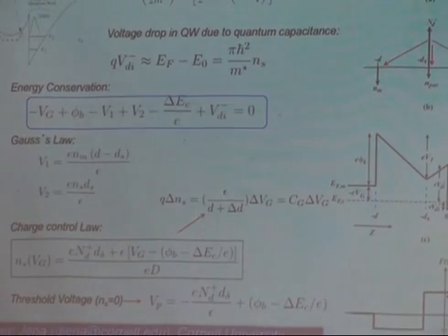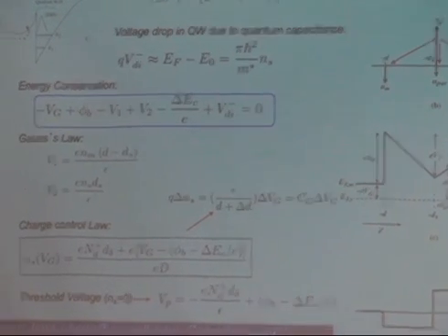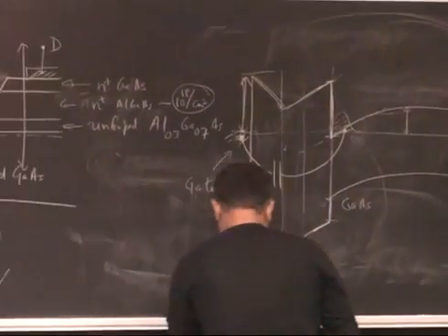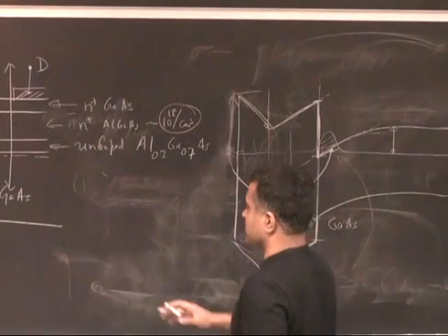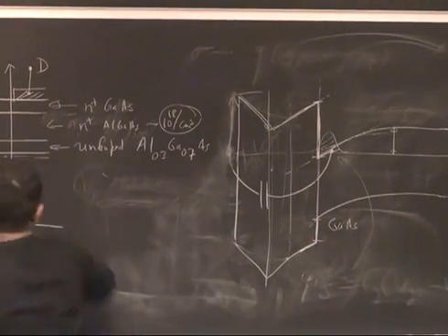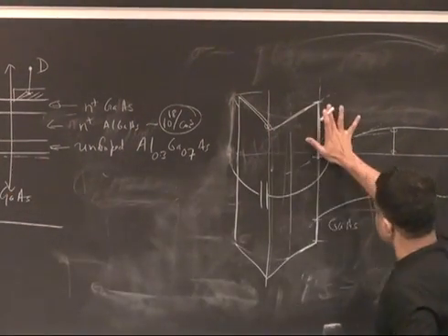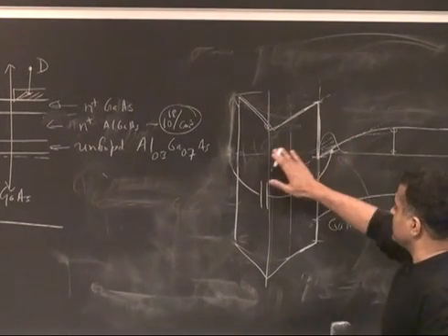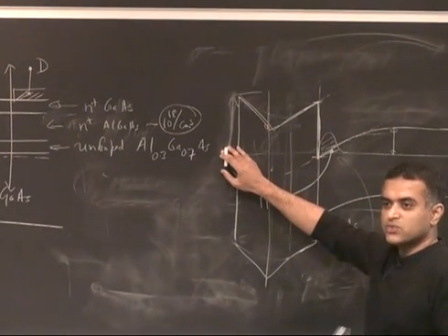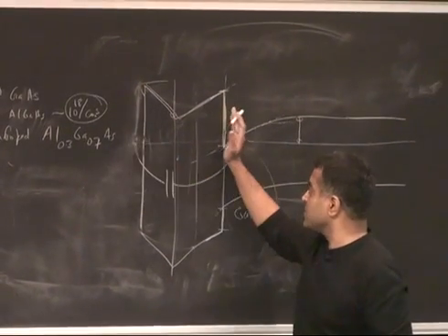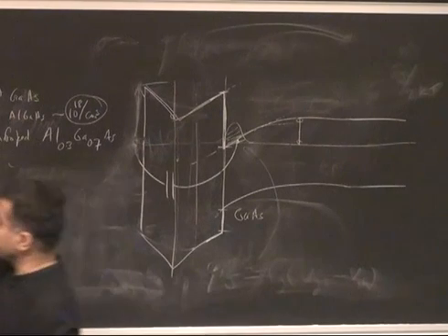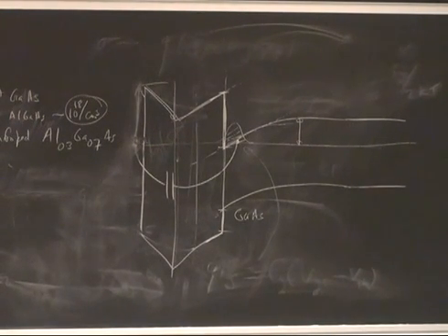So what we want to do now, that's the band diagram under the gate. Whatever I'm saying now, you can do in great detail and calculate accurately, but just from a pictorial perspective: if you have electrons in the 2D channel here, what sort of gate voltage should I apply to turn the transistor off? Positive or negative? I have electrons here which are going to conduct because they are in ohmic contact, meaning very low resistance between these two. This source is connected with a very low resistance to this entire 2D electron gas.